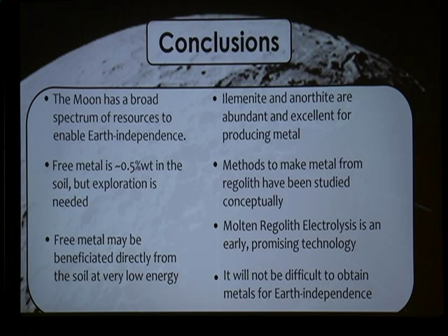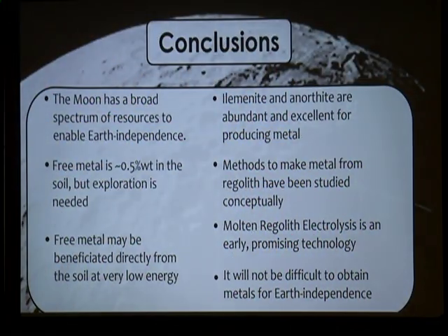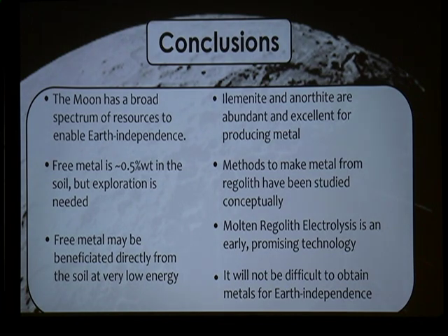For the sake of time, I skipped over a lot of this. So some of the differences are Earth has an atmosphere, which causes a lot of the burning off to occur at high altitude. And so large bodies survive some of the burning, but then because of the thermal gradients it creates in the impactor, it causes airburst, which decelerates a significant fraction of the material. Also, it fractions it into smaller particles, which would not have survived the early entry in small form, but it makes them small after entry. And because they're changed in ballistic coefficient, they can then slow down to a terminal velocity, which is sub-hypervelocity. And so things do survive on the Earth and on Mars.